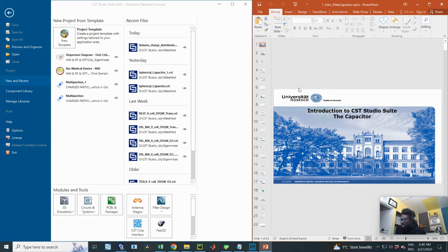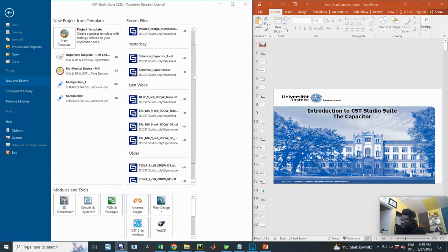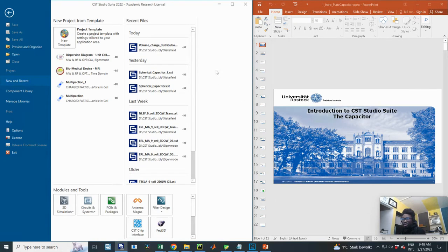I think the errors we had in class was due to us exceeding the amount of elements the license allowed. So if you notice any problem, just check the log file for the simulation. I would also show you. If you notice any problem, just check it and see if it's written there that the mesh sizes exceeds the permissible amount. So let's get right into the modeling.